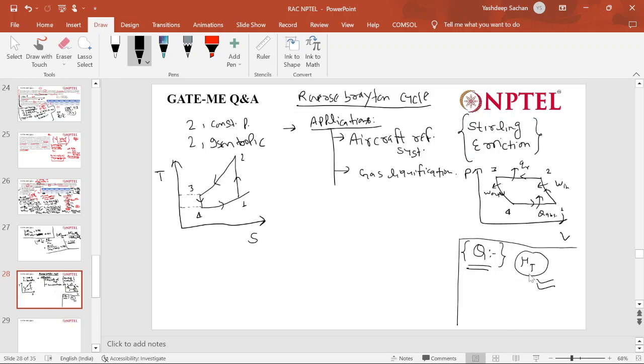What is the Joule-Thomson coefficient of air? Zero, sir. And here the working fluid is air. What is the Joule-Thomson coefficient? dT by dP at constant enthalpy. If the Joule-Thomson coefficient is zero, whatever pressure drop you give. Here what is happening? Here is some higher pressure, PH, constant. Here P lower, constant. Now let's suppose here you have given some dP. This pressure change will happen in the throttling valve. But what was the temperature difference there?